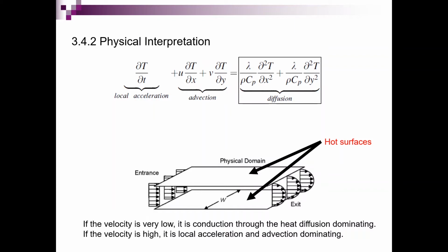The heat transfer from the surface to the fluid is not really that good because the fluid will become hot. That means as the fluid travels further, the heated surface is not going to be cooled down because the difference in temperature between the fluid and the surface is no longer significant. They're going to be saturated, which means that the temperature at the surface and the temperature of the fluid near the wall are similar, so no heat transfer occurs.